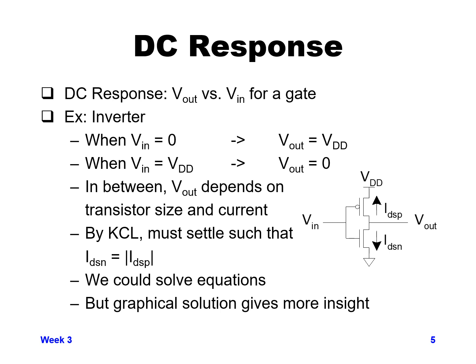on how much either the NMOS or PMOS are turned on and the transistor size of the PMOS versus the NMOS. Thus, how much each one is turned on, the voltage level, and the transistor size will determine the current going through the PMOS and NMOS.